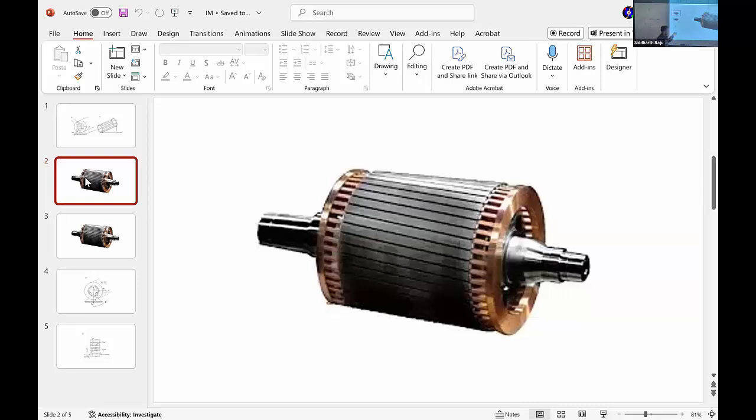All right. So the rotor structure, similar to even when you went to a permanent magnet synchronous motor, would have been similar, except there wouldn't have been slots on the rotor. You would have just stuck the magnet, at least for surface permanent magnet, to the rotor surface. In case of an induction motor, you would put slots into this rotor structure, put these copper bars and weld the copper bars on both sides. If it's a very high power motor, you will have copper bars.